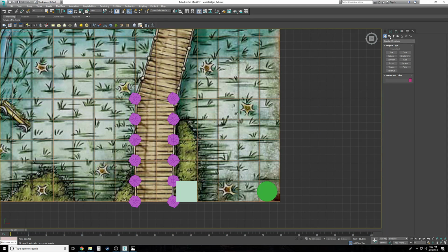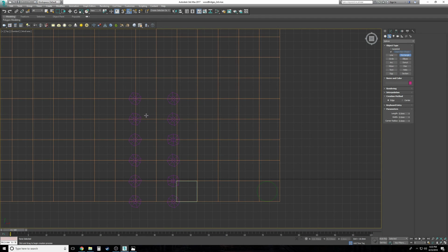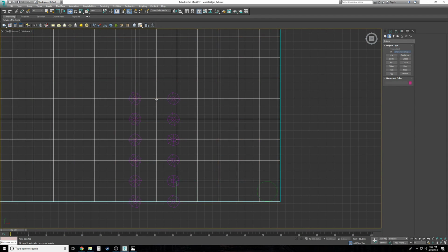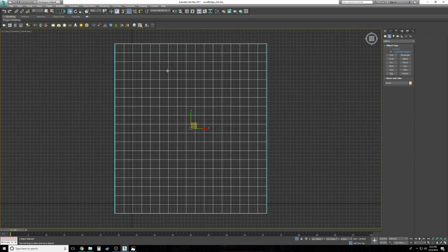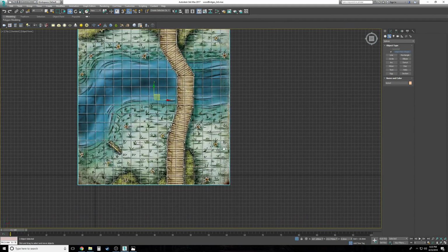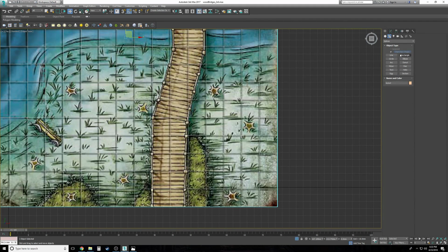So we're going to go to Spline under your Create tab. Second from the left is your splines. These are all lines that make geometric shapes, but they're all 2 dimensions. They're not 3 dimensions, which is what the button to the left is, which says geometry. We're going to make a rectangle. We're going to hit F3, and actually at this point we can just isolate just this map because we don't need the supports anymore yet.